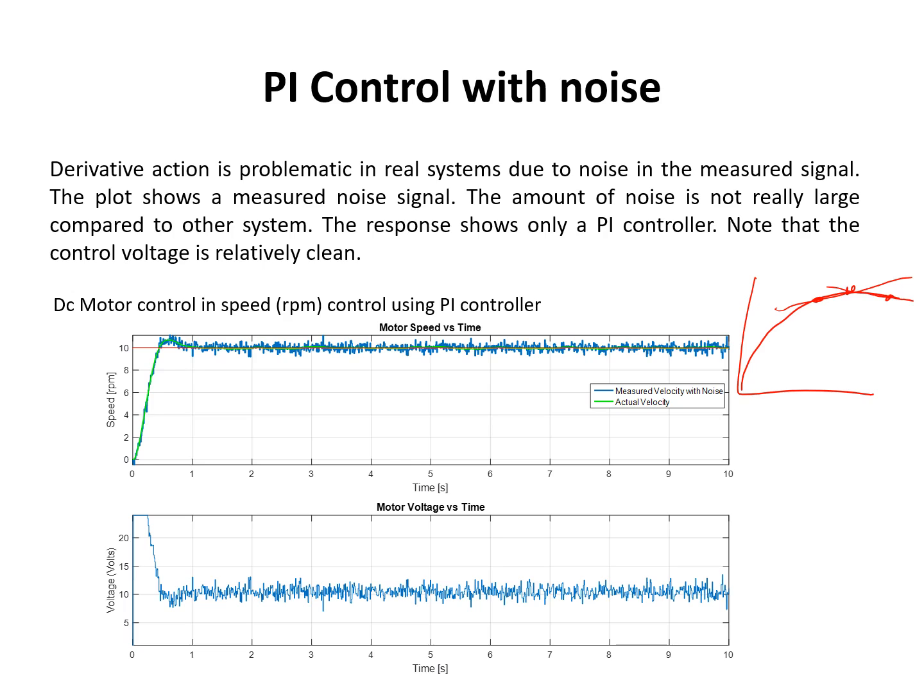So if our output, or our measurement, is quite smooth, then we'll get a fairly nice smooth derivative. However, what you typically get in practice is, instead of drawing a straight line for the ideal smooth case, for a noisy system, perhaps something that looks like that. So you'll have a derivative error which goes through those 2 points, then a derivative error which goes through those 2 points, and here, and so forth.